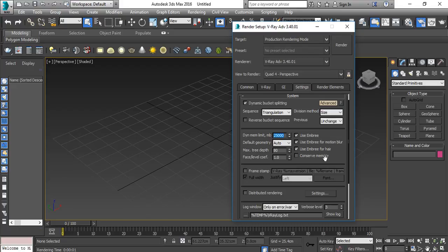So if you have 4 GB RAM, then type something around 2 here. If you have 8, maybe 5 or 6 or 7 GB, whatever you want to choose, because some RAM should be available, because while learning, if you want to use the internet or any other software, it should be there, because when you are rendering, it is hardly possible to do something else on your machine sometimes if your machine is not good, right?